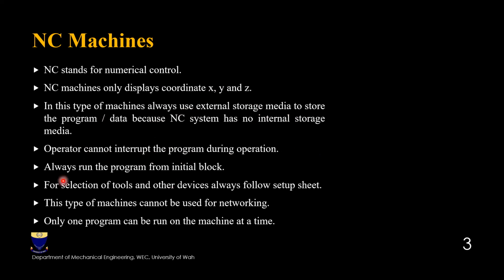This is a rechecking: always run the program from the initial block. For selection of tools and other devices, always follow the setup sheet. This type of machine cannot be used for networking. Only one program can be run on the machine at a time.